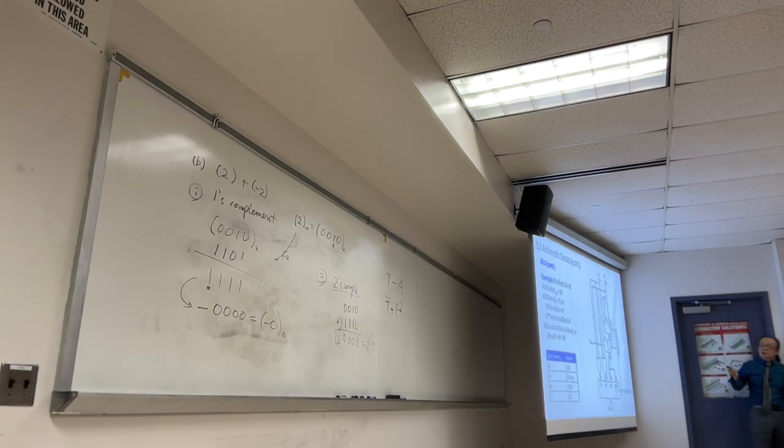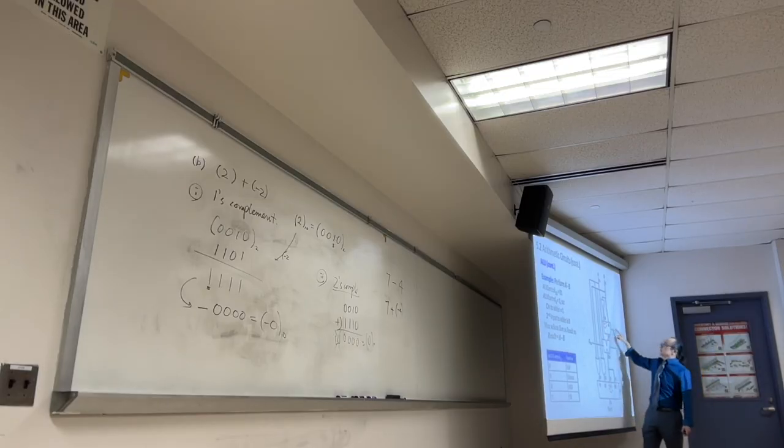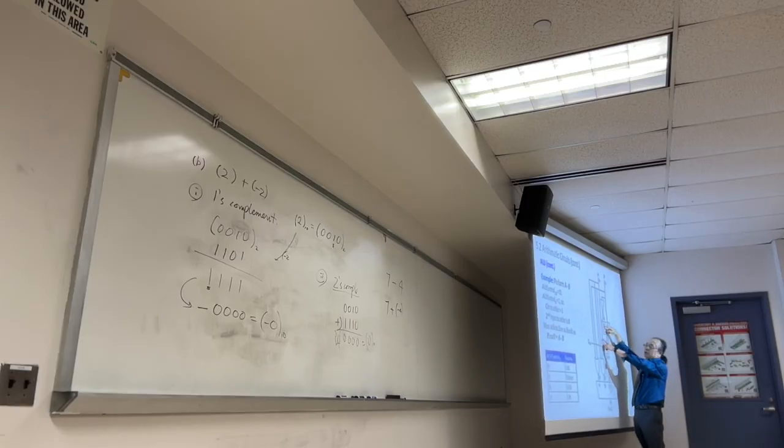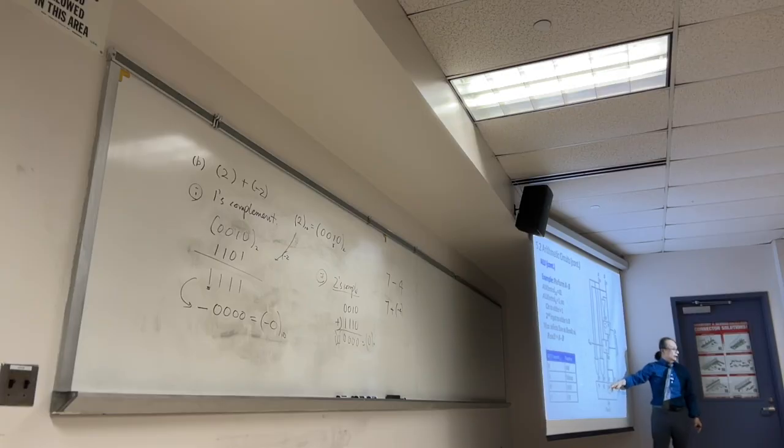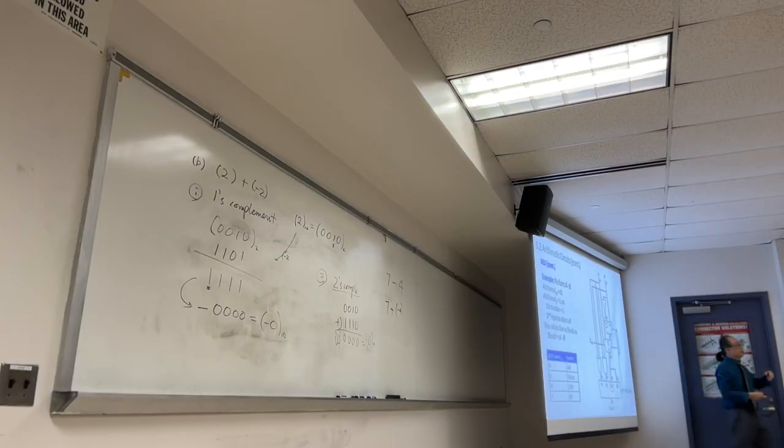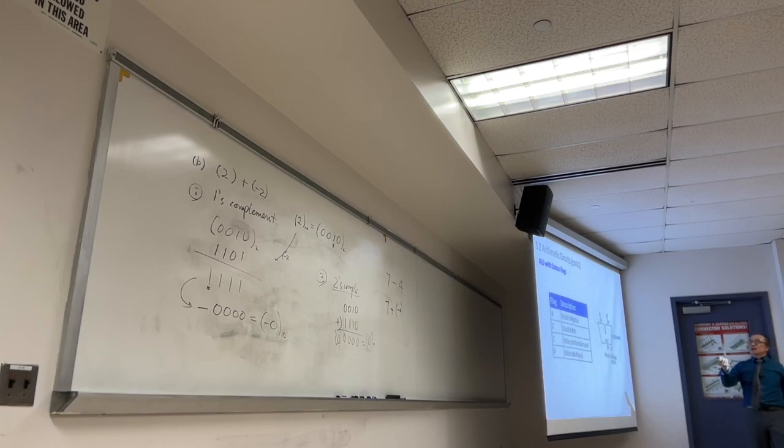Very straightforward. The same way for the subtraction, now we're going to select here, this guy is going to be 1, and then for here, we're going to add them up. But when you add, because we select 1, we're going to feed it 1. So flipping the bit plus 1. So here is a 1's complement, adding 1, making 2's complement, and go through here. We produce the subtraction. Next, the ALU with the status flags.